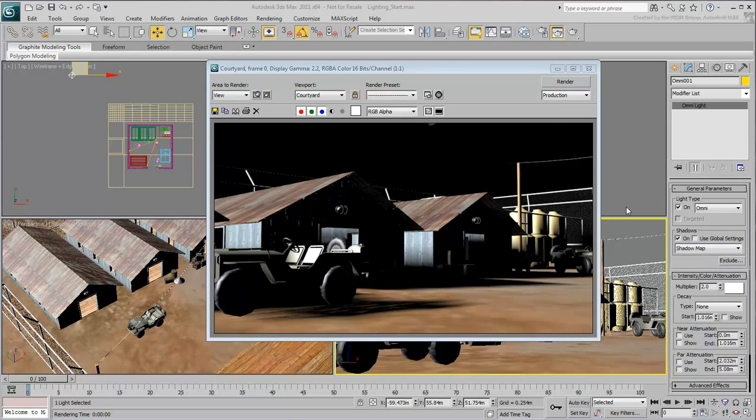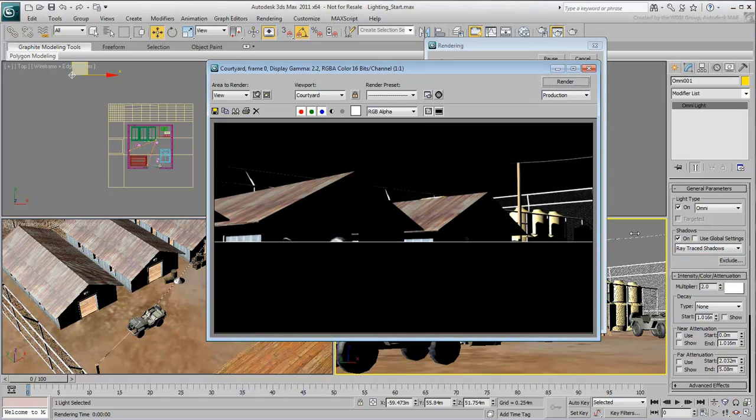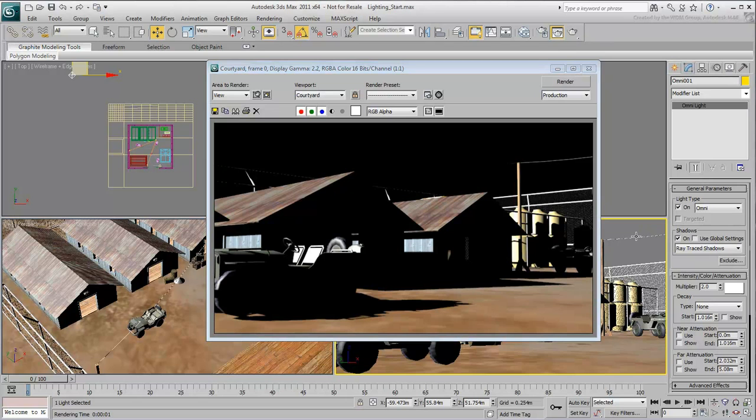Shadows display, but they don't look very accurate. The default Shadow Maps option is fast to calculate and produce soft shadows, but Shadow Maps only approximate shadow projection. From the Shadows drop-down list, choose Ray Traced Shadows and render again. This time, the shadows are crisper and more accurate.